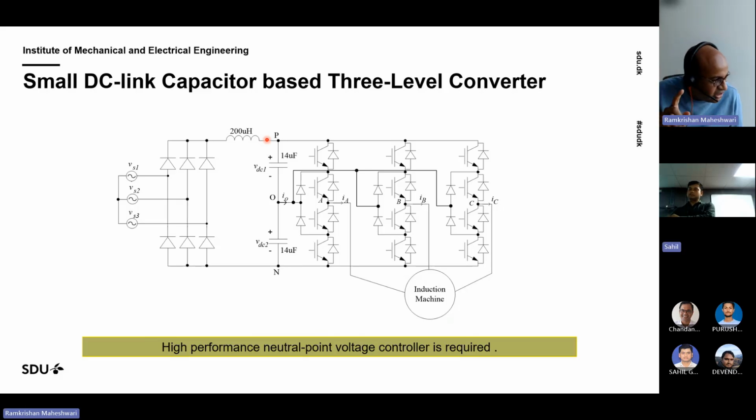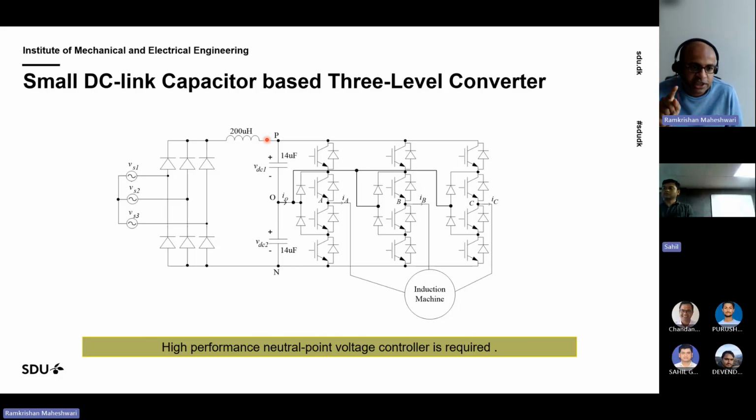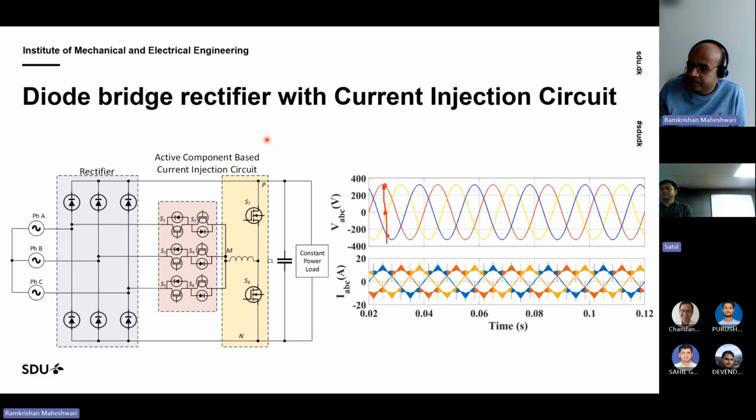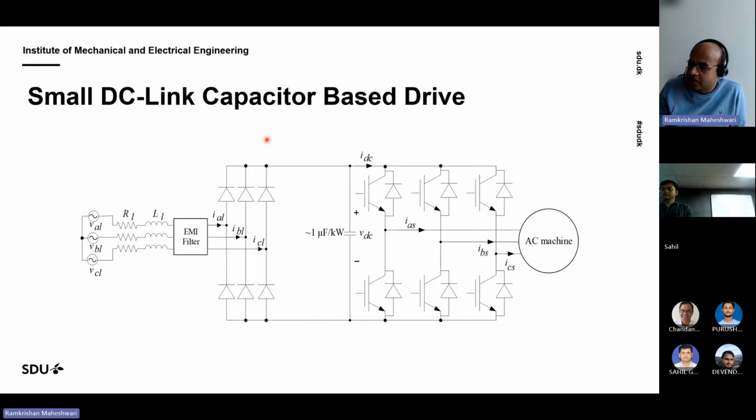There is another paper which I have written. What you can do, instead of taking the instantaneous DC link voltage, is take the average value of the DC link voltage to calculate the reference signal inside your microcontroller. Then you will not have a negative impedance instability.